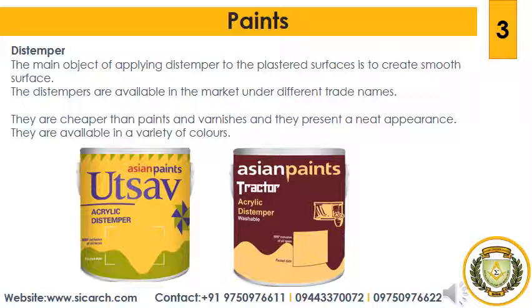They are generally light in color and they provide a good reflective coating. They are less durable than oil paints. So they are treated as water paints and they are easy to apply. They can be applied on brickwork, cement plastered surface, lime plastered surface and insulating boards. They also exhibit poor workability and they prove to be unsatisfactory in damp locations such as kitchens and bathrooms. So next we will see the ingredients of distemper.